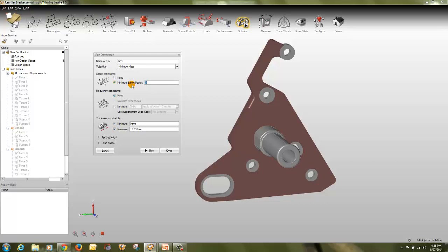Once optimization is complete, the best result with minimize mass is found by dragging the topology slider far right in the shape explorer window. The optimization result is the point at which all the loads and support locations are connected. So this will help us to define these constraints.